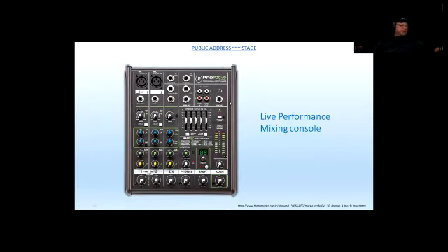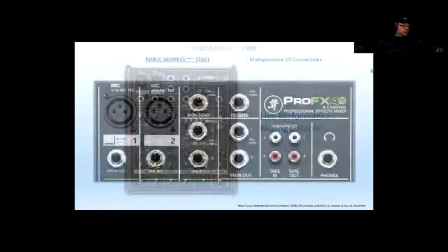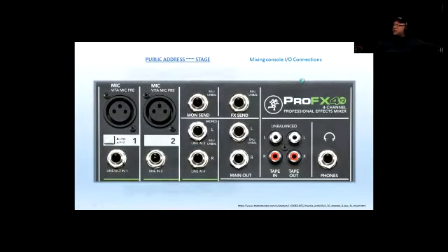Okay, right now we're going to zoom in to just this part right here. See those two microphone outputs? The top left ports are for balanced signals. Yes, exactly, there you go, Tyler. So these are the XLR inputs, the balanced inputs. Now for this channel, this is a 4-channel mixing board, but you can have 2 balanced inputs on this one here.